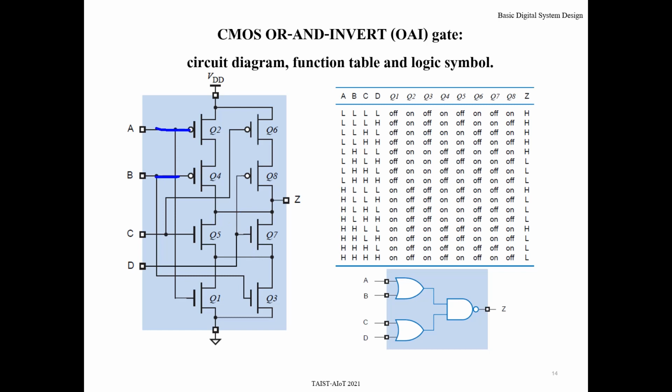for this one A, B, A here. This one is controlled by C. So this one is A, this one is C, this one is D, this one is controlled by B. And now note, the transistors Q1, Q3 controlled by A, B connect in parallel together. This one and this one are parallel together, and this one parallel together, and this is in series together.